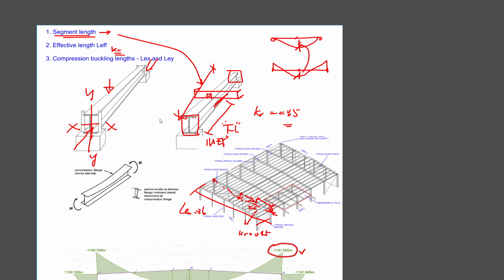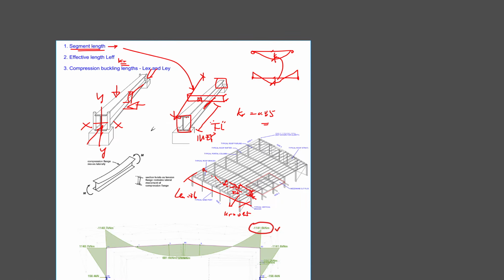But in terms of the minor axis, there's buckling through the web region and out-of-plane region. So what's stopping that? There are many things you can do to stop that beam or column from buckling about the minor axis. You can create fly braces, and you can do welded cleats to stiffen it. And there are a lot of things you can do to protect the minor axis of the beam or column.